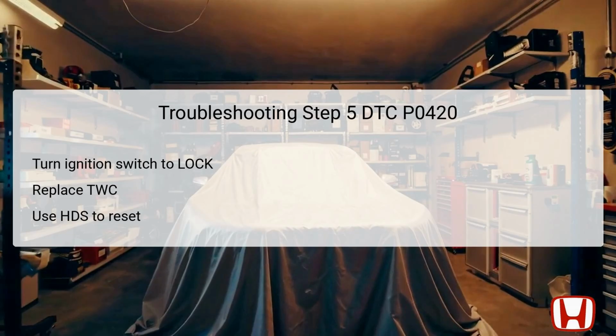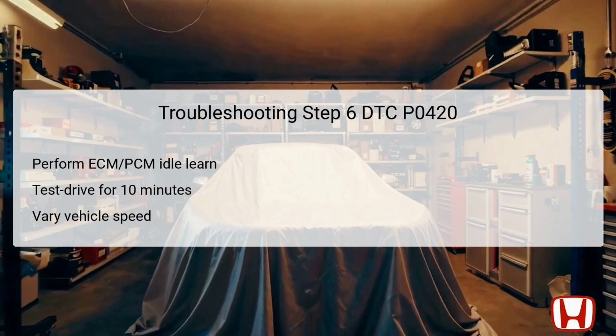This reset ensures that the newly installed catalytic converter is recognized by the vehicle's onboard computer, allowing it to function correctly. After resetting the ECM-PCM, it's crucial to perform the idle learn procedure. This process allows the engine control module to recalibrate the idle settings based on the new conditions established by the updated components.